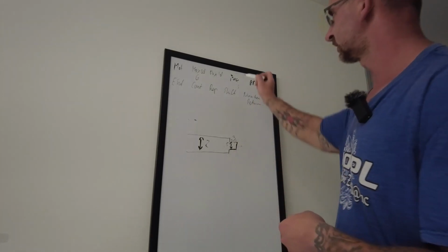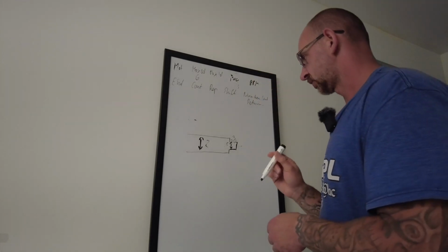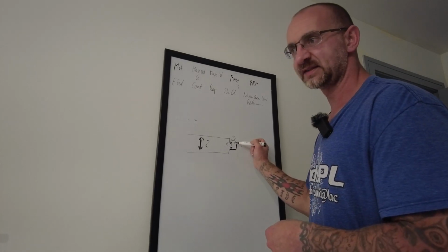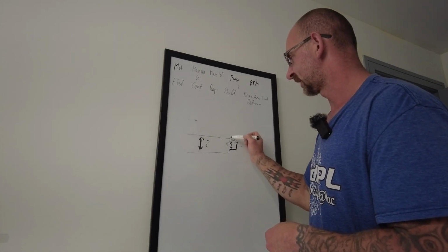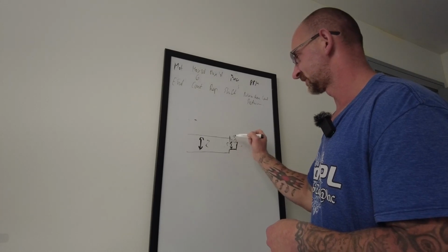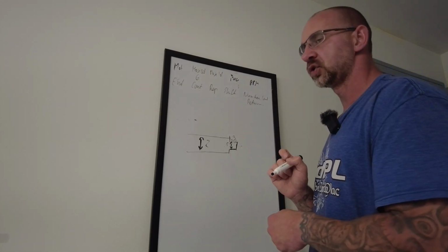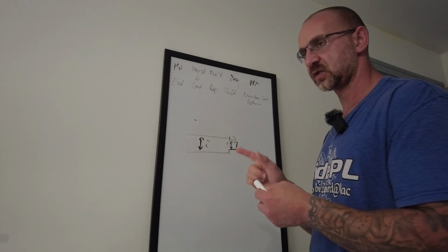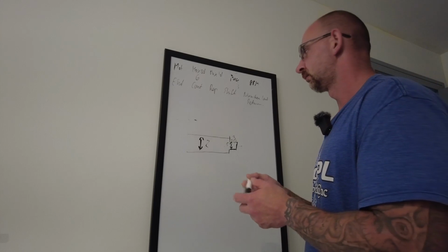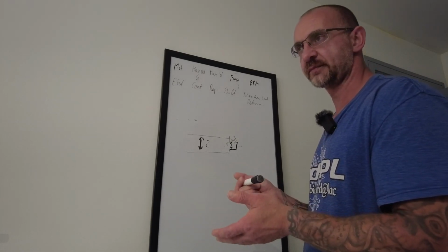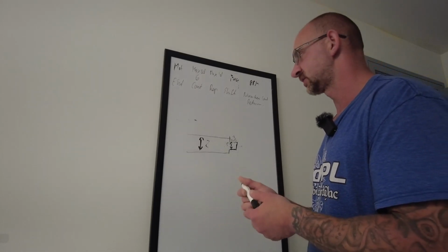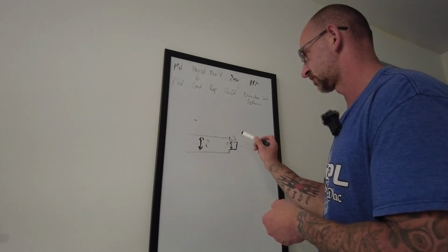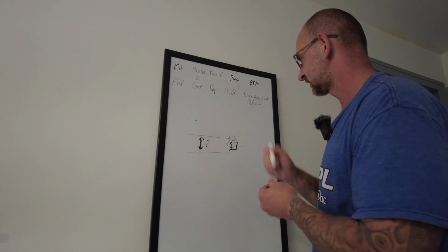Okay, so 300, 300. So what you can do is you can touch this off, set this as a minus 300, so the machine automatically is gonna set this section where we want it as a 300, right? And then let's say you do OD turning, so you go bar out, your cutting position, your starting position on X is gonna be 2 inches. Your starting cutting position on a Z is gonna be minus 300, right? When we program, and this is our 0,